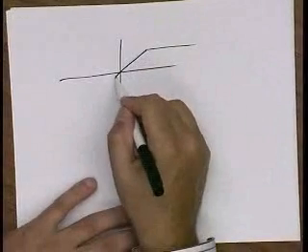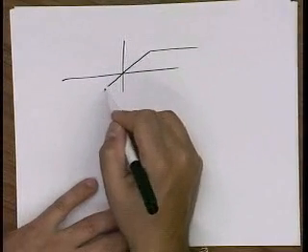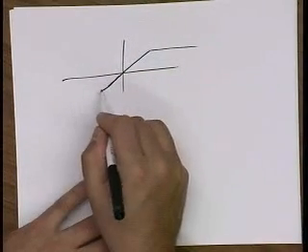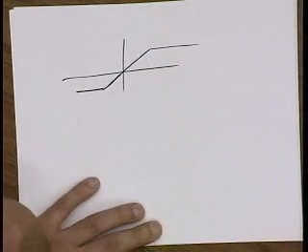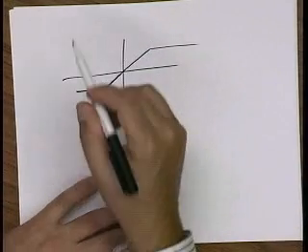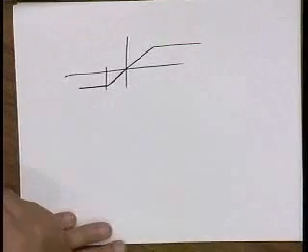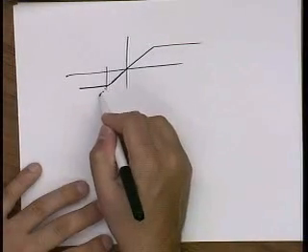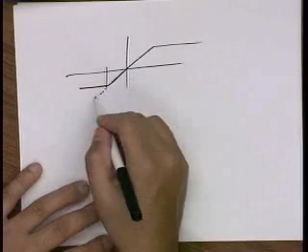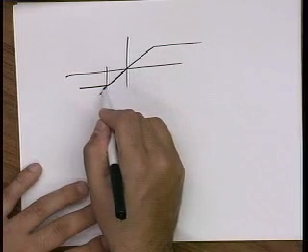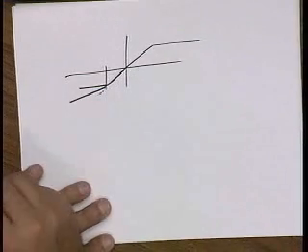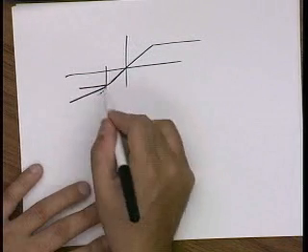On the negative side, though, I could get into a situation, if I haven't designed this right, where I actually saturate out because the input common mode voltage is getting too low, right? Now, by adding the second stage, my gain is going to drop, right? So the slope of this curve changes, but the PMOS is still alive.